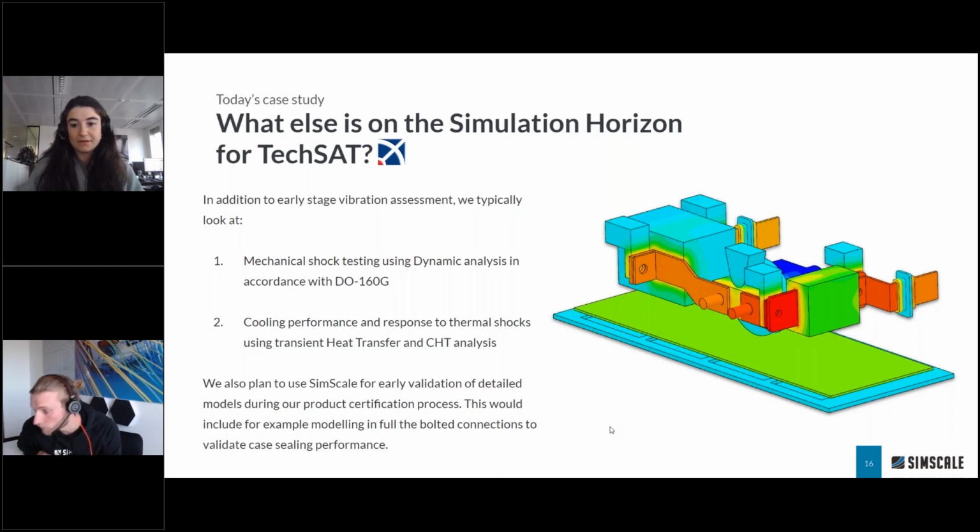So we've got one question around damping in the harmonic analysis. Yes, very good question. If you have material damping information for your particular materials, then great. Then you can just apply that damping ratio, so ratio to critical damping. But often the case is we don't actually know what the specific damping is for our materials. So the best approach is actually to do a few different simulations.